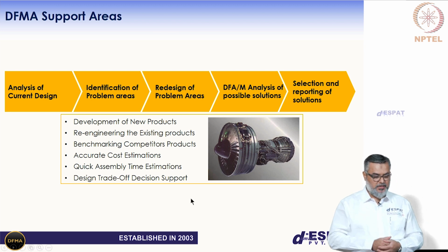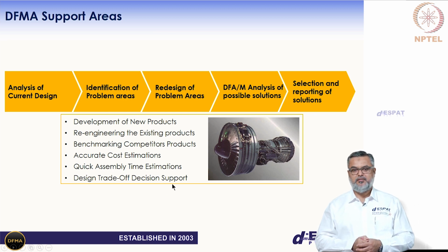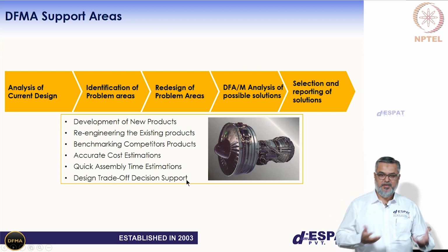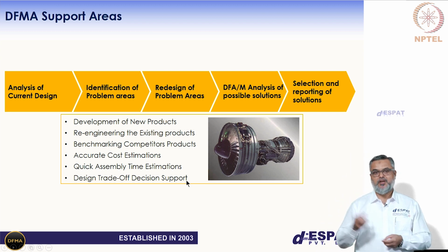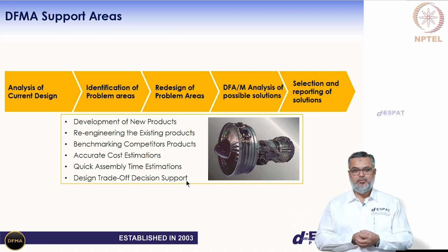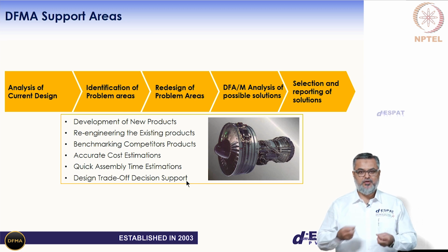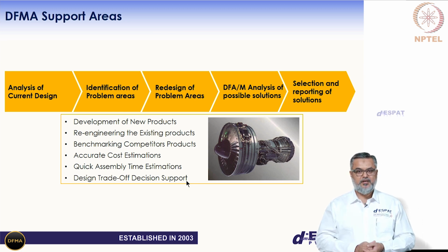Other things that we do is investigate and reduce shop floor time by making the assembly even more elegant and more efficient. And the other opportunity is to make trade-off decisions. Today I am making sheet metal, what if I make it in plastic? I want it in casting, but I do not like sheet metal. So, what opportunities of volume do I have to provide to my vendor or myself in order to build it at a fairly profitable cost?